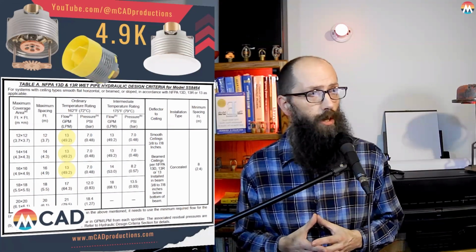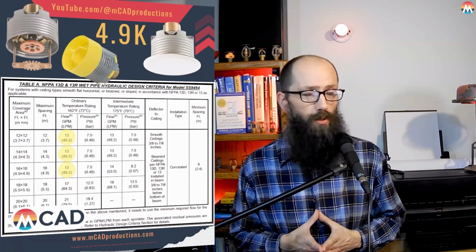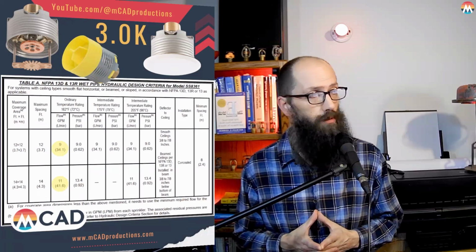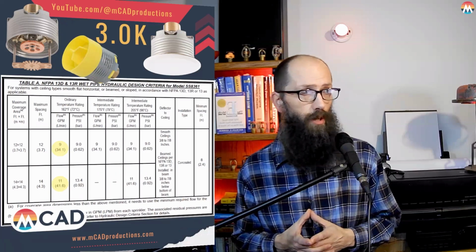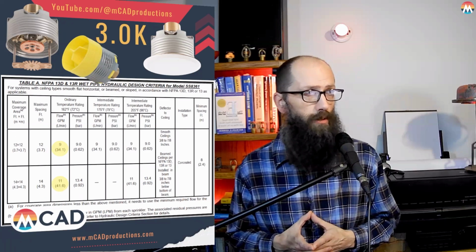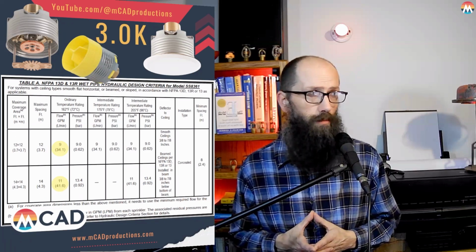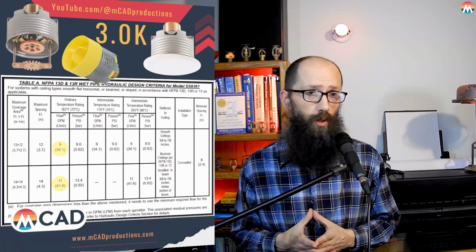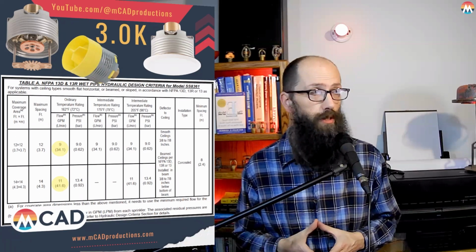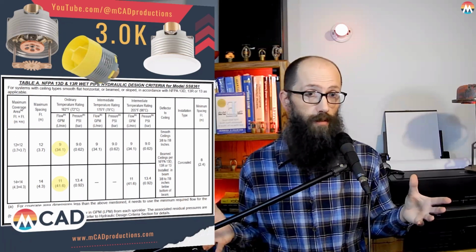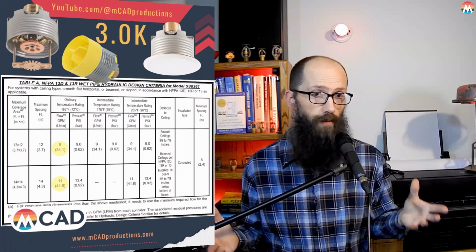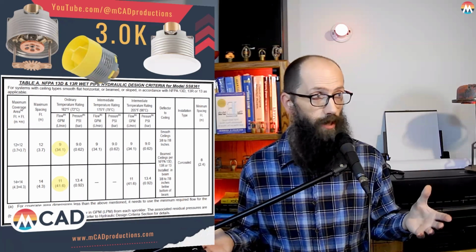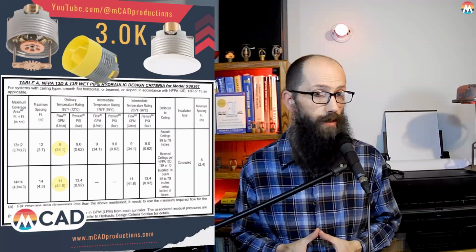So there are ways that you can play around with your sprinkler heads. If we go to a 3.0 sprinkler, we can reduce our water demand down to 9 GPM for a 12 by 12 spacing. And we know we need a 10-minute supply for 13D. So if we now only need 9 GPM out of 2 heads, that's 18 gallons a minute for 10 minutes. That's 180 gallons. So you only need a 180 gallon tank now.